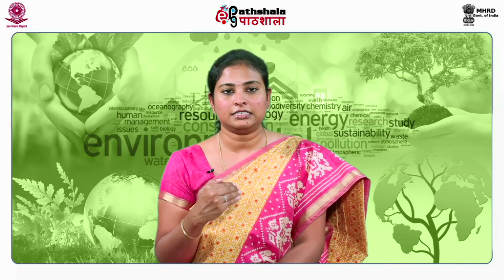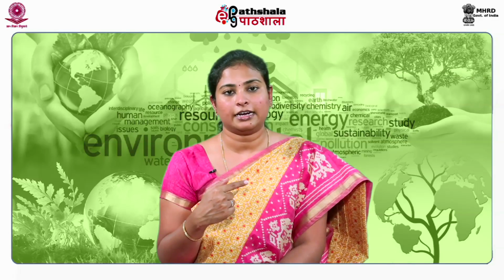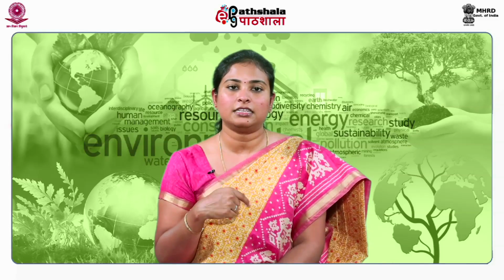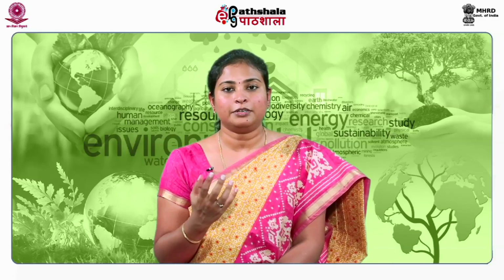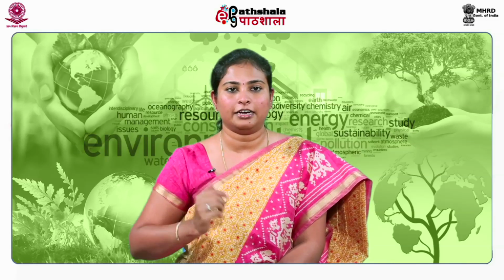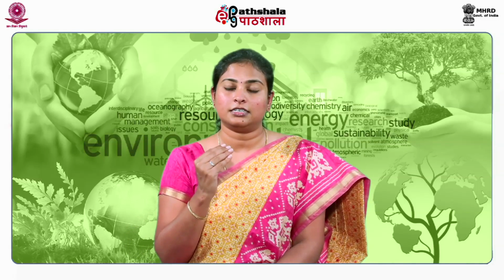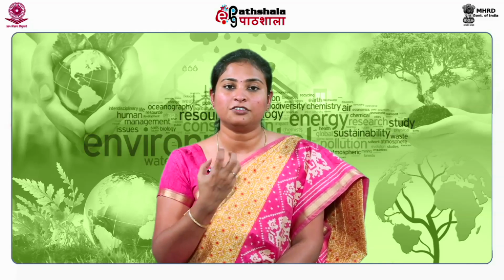Now, the next parameter is temperature. You should continuously monitor the temperature within the landfill bioreactor because it will indicate the stage of biological activity within the bioreactor. Temperature monitoring is very essential, especially in aerobic landfill bioreactors, to avoid fires, because sometimes the waste can catch fire.